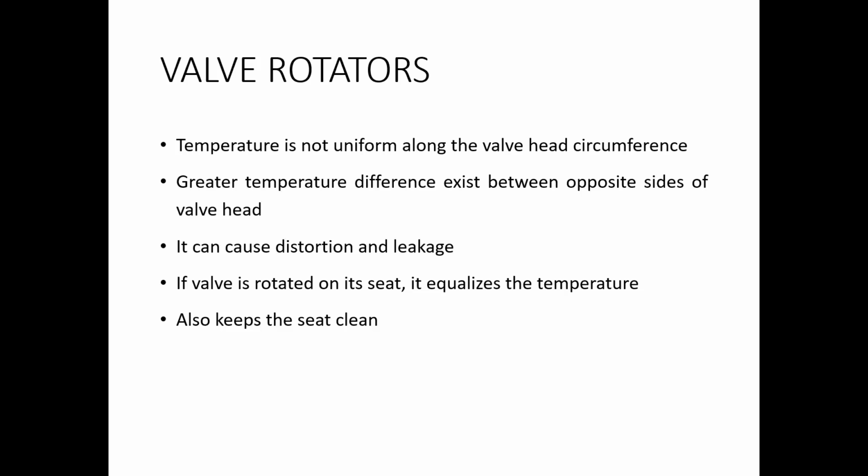This ensures that the heat is not concentrated at one particular area of the valve. Each time, different regions will experience heat, so that cooling can take place quickly, and premature failure does not occur due to the concentration of heat at one particular place.